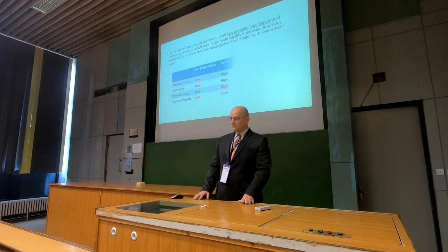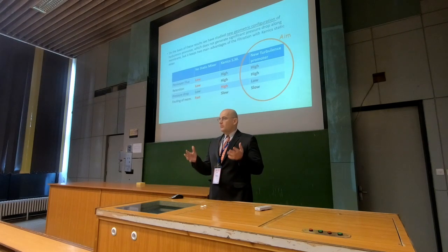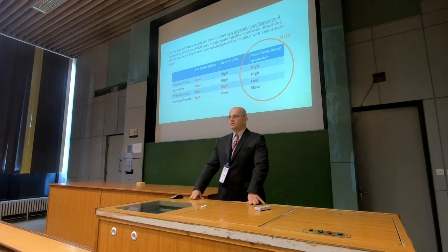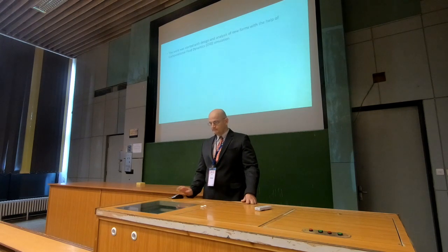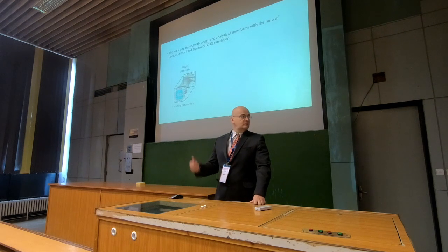And on the basis of these results, we have studied new geometric configurations where our aim is to find a turbulence promoter which will keep the advantage of the Kenix static mixer, but will not cause the higher pressure drop along the membrane. The work was started with design and analyzing of new forms with the help of computational fluid dynamic simulation, the CFD.